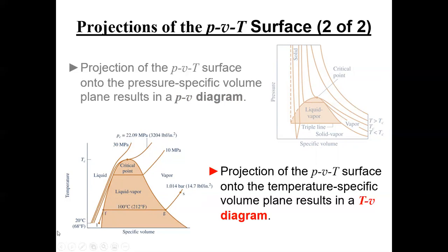If we continue to heat and maintain that constant pressure, we will start to boil the water. It boils all the way across until we get over here at G, in which case I have 100% saturated vapor. And if I continue to heat, then I will start increasing temperature at constant pressure, if my process allows me to maintain a constant pressure. You have to have the right sort of apparatus for that in order to do the experiment.